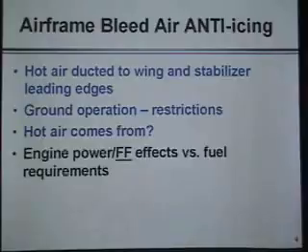Okay, guess what? 45? Okay, fine. 45 minutes. See if I care. Okay, you're going to get that. Yeah, so much for your extra credit project. Yeah, that's right. Day VFR is 30 minutes, and night and IFR for airplanes is 45. And that's the same, plus having to go to your alternate. And that's the same Part 91 or Part 121, by the way.